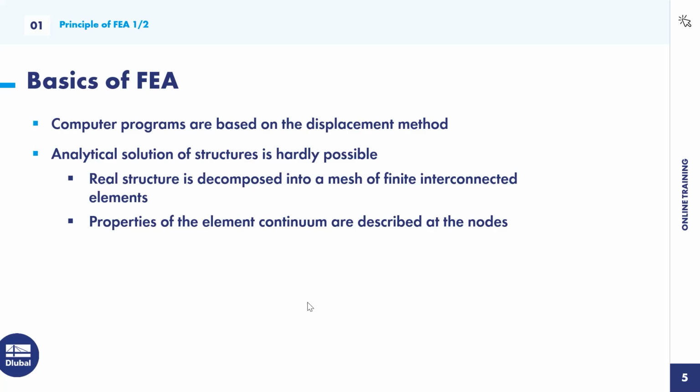We will have, on the one hand, connections between two finite elements, and within these connections we have linked degrees of freedom. I mean, you can imagine a plate connected to another plate, and at their intersection, let's say, the deformation in the z direction, so in the vertical direction, must be the same. That would be one example.